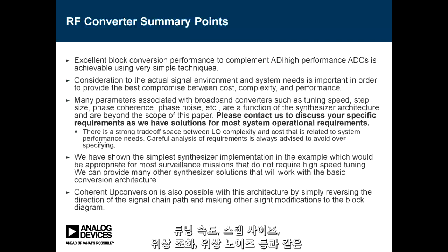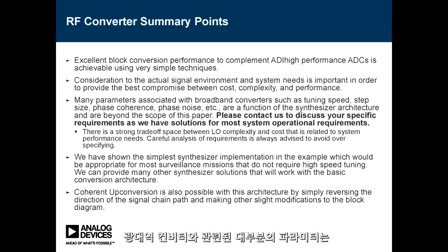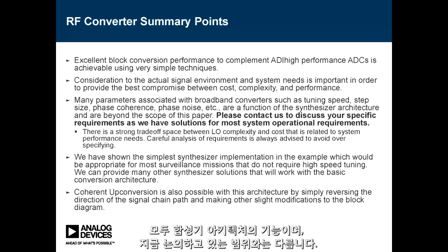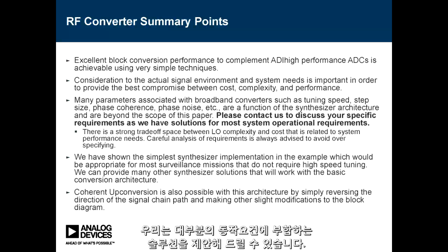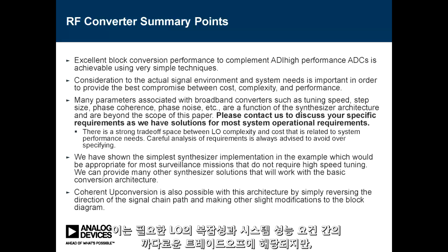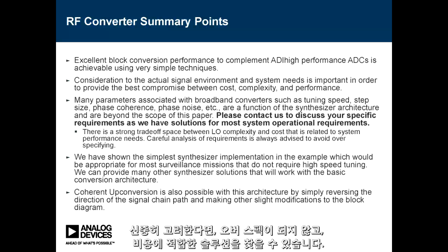Many parameters associated with broadband converters, such as tuning speed, step size, phase coherence, phase noise, etc., are all a function of the synthesizer architecture, and they're beyond the scope of this paper. So just let us know to talk about your specific system requirements, because we have solutions for most operational requirements. It's a tough trade-off space between the LO complexity that is required and the system performance needs, so you have to be really careful that you don't overspecify it and drive the cost up.